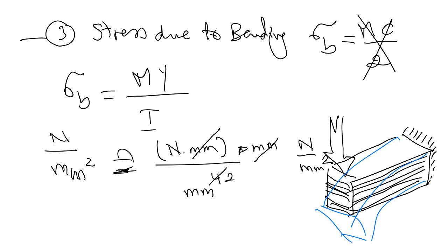So now, guys, we need to clarify something. If you look at the upper layers, of course, we are assuming that this stack of paper is still in the same plane. So if you are assuming that your stack of paper is still in the same plane, this means that for the beam to take this form, the upper layer should be extended. You agree, guys?